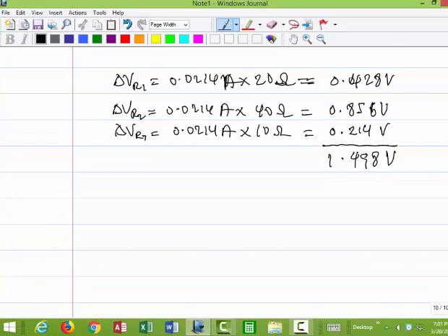Yes, it was my fault to just make it 0.02. I was trying to make it simple, but in this case, to illustrate the point, I should have left all the decimals in, just to point out to you that it is exact. If the EMF is 1.5 volts, then the potential drop across each element, if you add them all up, you should have the same, 1.5.